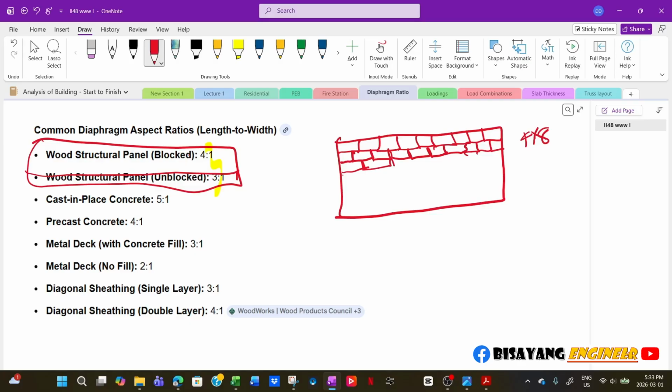Now, if you remember, our truss spans this way. That's why it's better to span your trusses by a multiple of the dimension here. So your spacing could be 12 inches on center, 19.2 inches on center, because 19.2, if you multiply it by 5, that becomes 8 feet. Yeah, 5. If you multiply 19.2 times 5, it will be 8 feet.